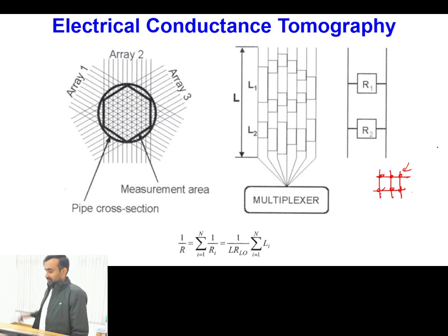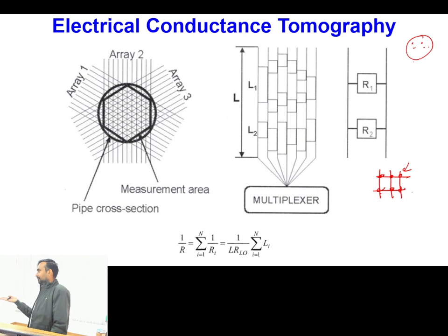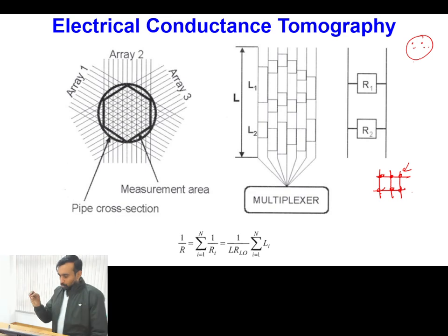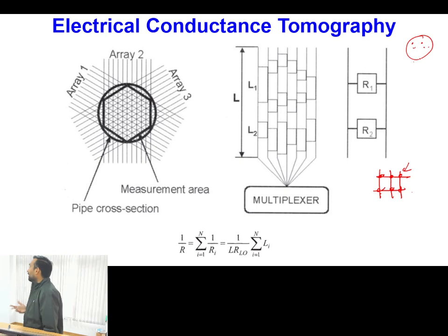So till now we are saying that at the pipe cross section, at a large number of locations, we will be measuring the indicator function. Indicator function means which gives indication whether you have liquid or gas present at that point. But if we have to get the data, then we also have to devise some mechanical arrangement which can give me this data.